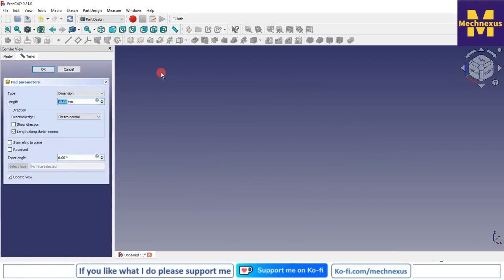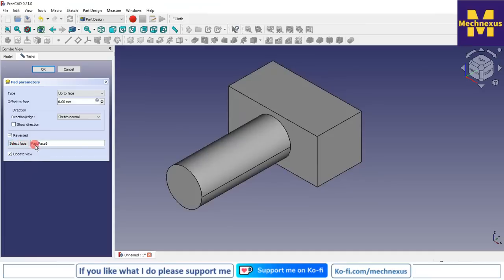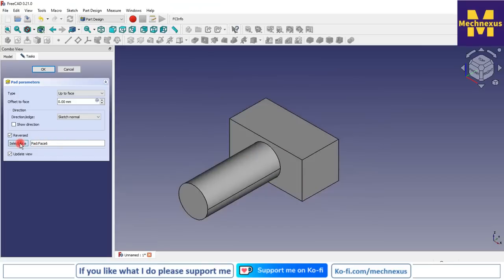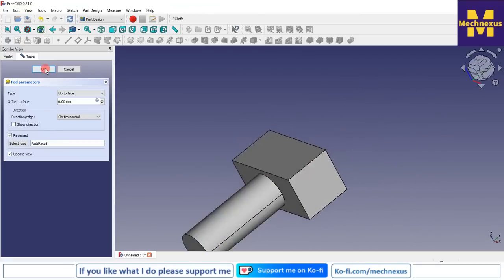So you will see that you are not seeing anything on the screen. For this click on reverse and from here click on up to face. So here I will select this face. So you can see that this extrusion goes up to this face. Here you can see that the selected face is pad F6. So if I want to change my face, then I can also select my back face. So the extrusion goes up to that back face.